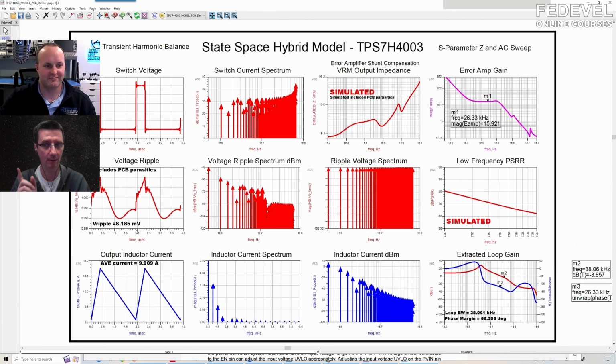I would like to highlight, sorry for interrupting, but I really would like to say how important these PCB effects are for the circuits. You can see it's just copper and capacitors, and they make a huge difference, because there's inductance and everything. I'll put it this way: if you're not including PCB effects in your power supply or power integrity simulation, your answer is always wrong. It will never be right.